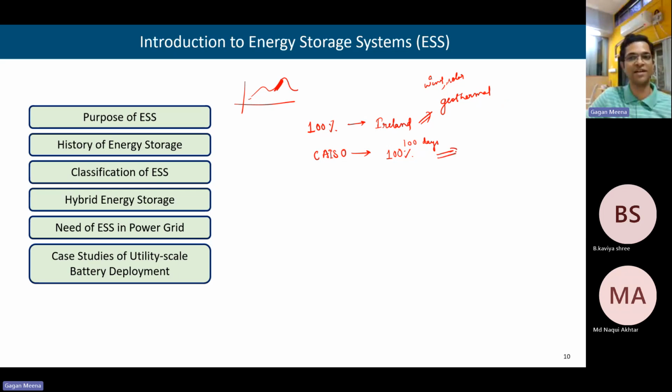Here, California ISO is doing that with the help of hydro resources. So they have been able to operate the system with 100% renewable for around 3 months because of the usage of hydro for the ramping, for meeting the flexibility requirement.